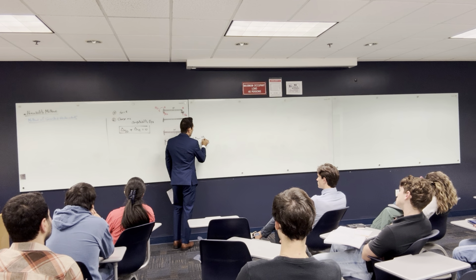If you want to find M final, it's going to be equal to the MO that comes from the main system plus F, the force, multiplied by M1. If you want to find shear, the final shear QF is going to be equal to the shear that comes from the original system plus F multiplied by the shear that comes from the other system. So these are all the rules that you need to solve a problem like this. Basically, we divided our problem into 2 problems and we tried to solve them.